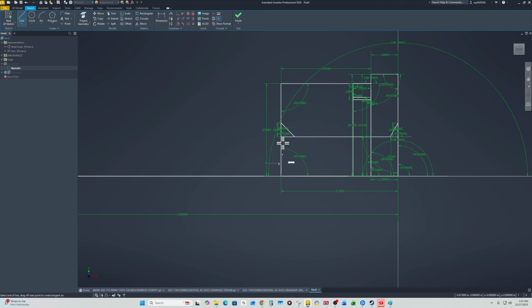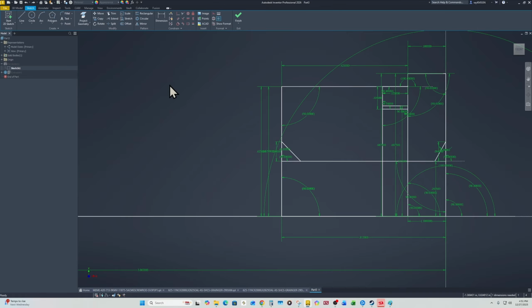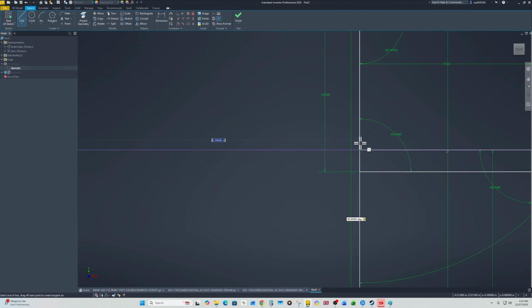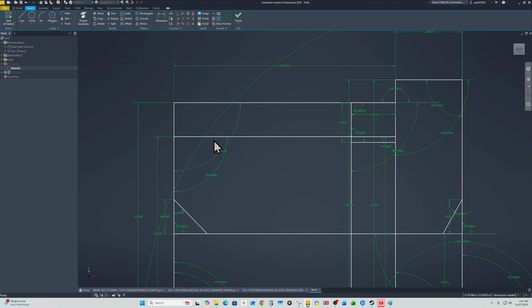So I'm gonna go over here. I'm gonna start a line right there, and I'm gonna do 1.25 divided by 2, tab 9, tab enter. Oh. It's not 1.25. Oh shit. Okay, cool. So it's 1.063 divided by 2. Alright, whatever. Start line here again. 1.063 divided by 2, tab 9, tab enter. Tab 90, tab. Oh, I already had a reference right here.